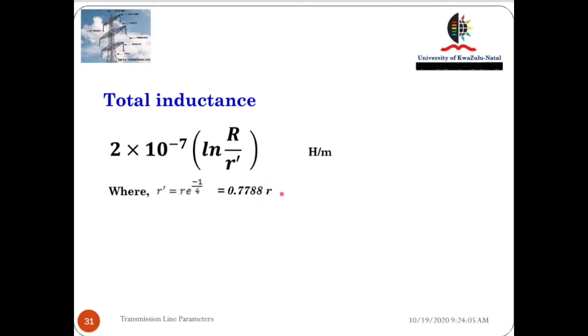So this is self distance. We call it own distance. Because of its own radius, it will have its own distance. So the distance of the conductor itself, being the conductor radius or the dimension of the conductor, is related here, and the distance of all other conductors from this conductor is going to determine total inductance of the conductor, which is the very unique equation here.